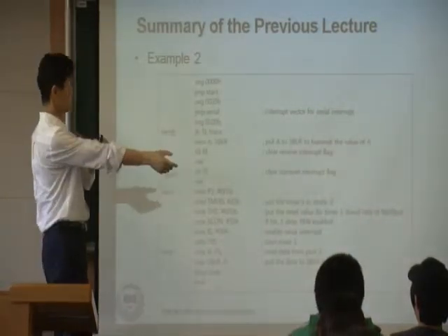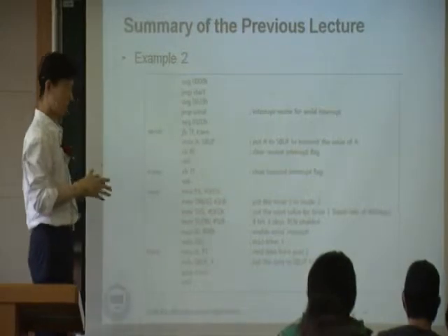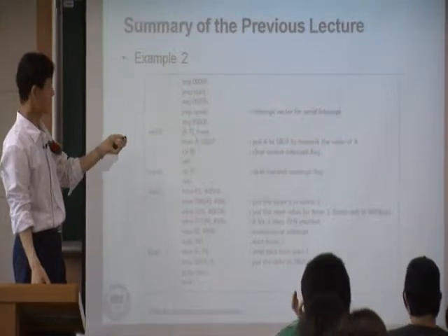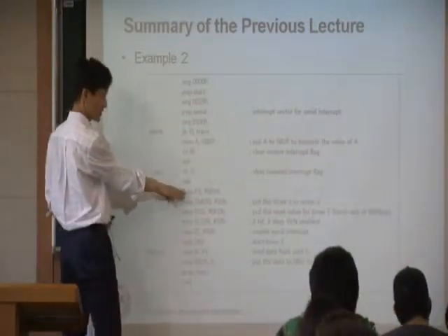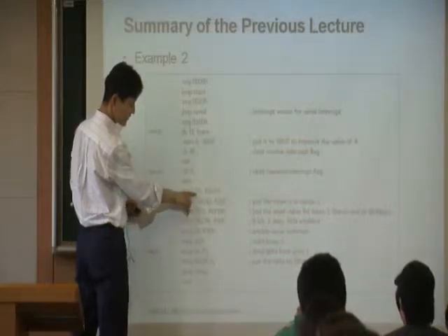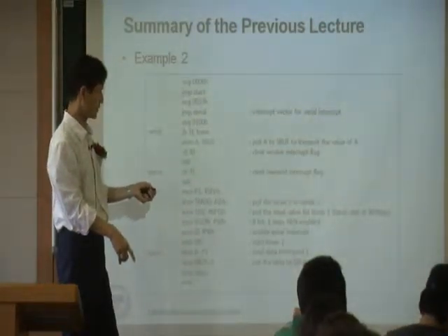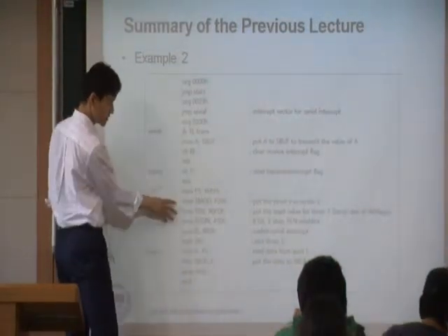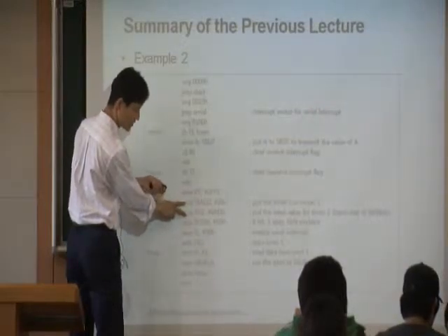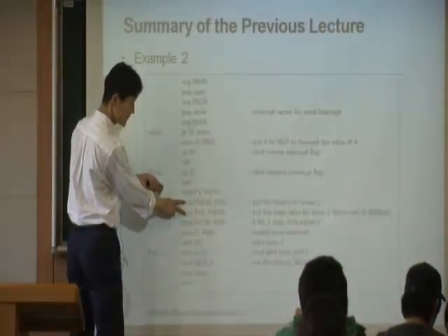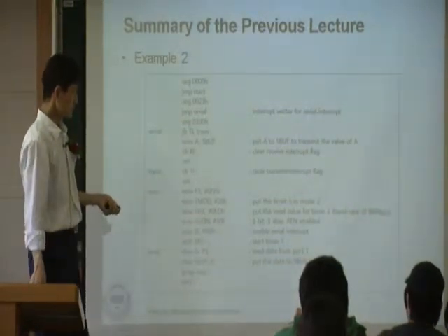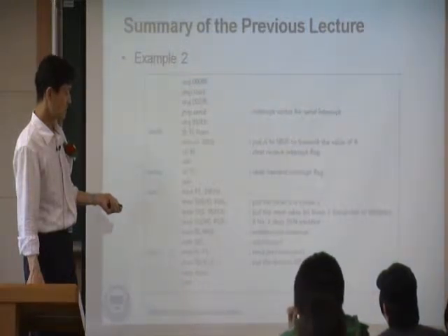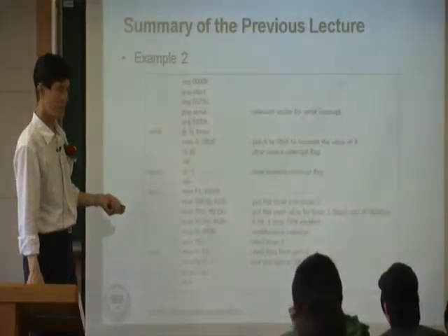Let's look at example 2. In example 2, right here, again, we have a reset vector, jump, start. So let's jump to start here. This is where my program starts. In my program, first of all, I set my port 1 to FFH. And then the next 2 lines, I set the timer, in a similar way. Okay, configure the timer. And also the next line, you see MOV SCON, 50H. So this configures the serial communication block.